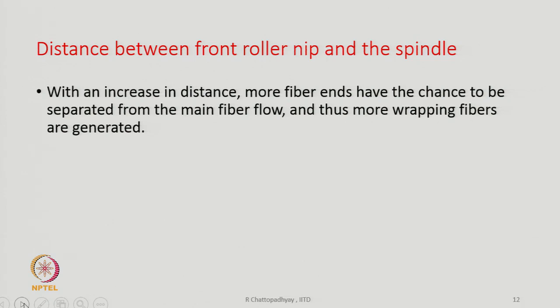Distance between the front roller nip and the spindle. With an increase in distance, more fiber ends have the chance to be separated from the main fiber flow, and thus more wrapper fibers will be generated. So, that is also a very important distance. The distance between the front roller nip and the entry to the jet is also very important.